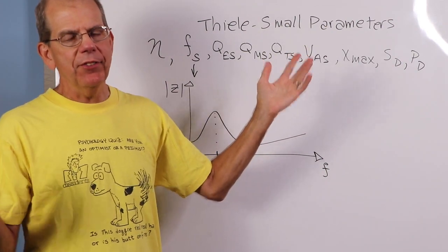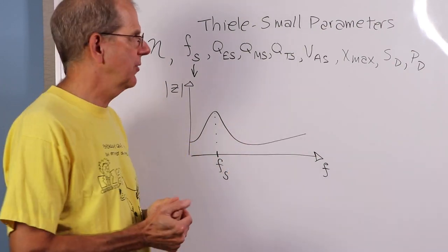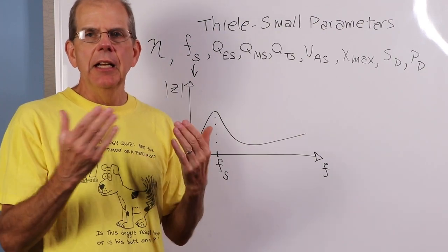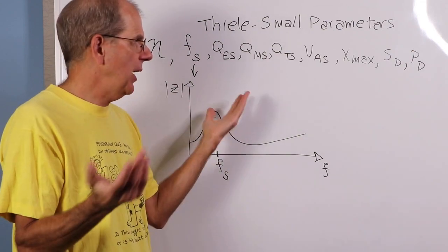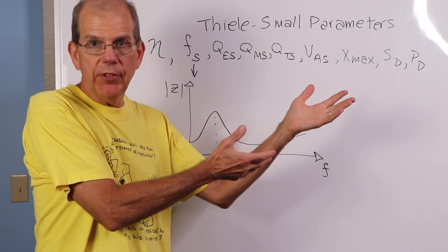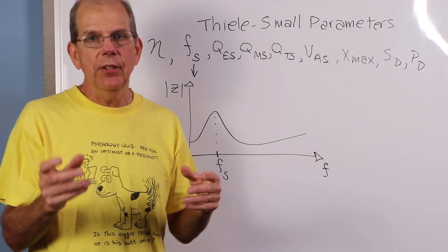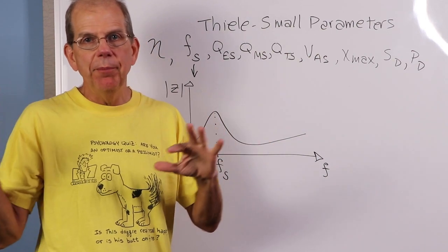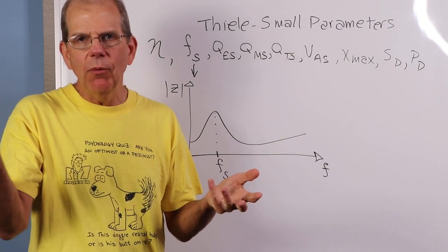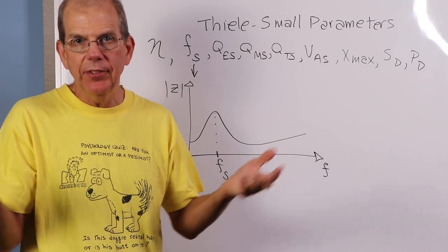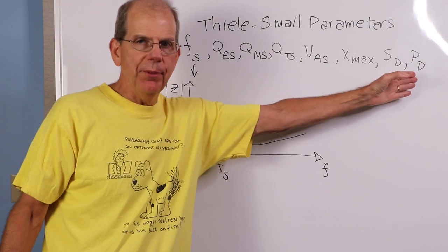Manufacturers can come up with other things. They might say, well, we have peak impulse music power or some crazy thing like this. How does that relate back? I want everything to be measured with the same standard, right? So if I have one loudspeaker rated at 100 watts sine wave RMS, and I have another loudspeaker that's rated at 200 watts, but it's some kind of magical impulse music power or something, I can't say that second one has twice the power capacity because, what's the comparison between those two measurement standards, right? So you want to be consistent about that.